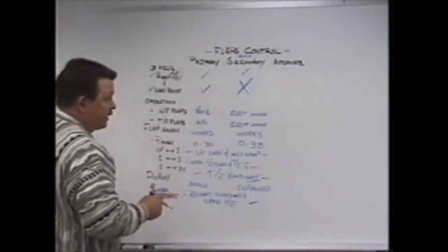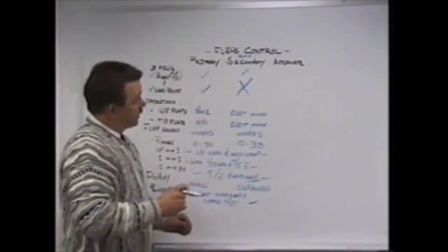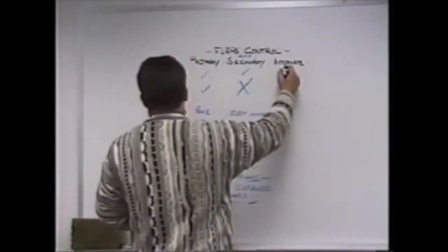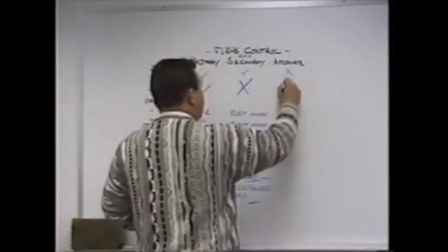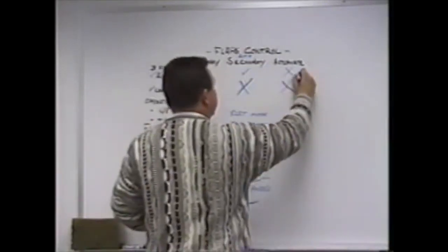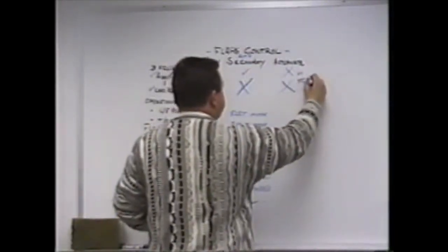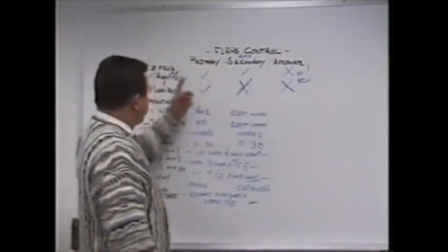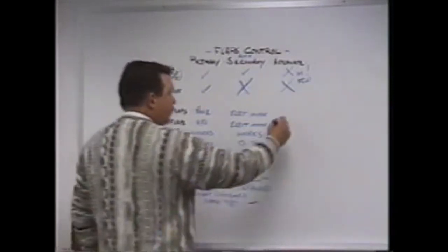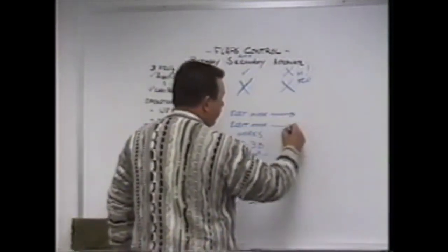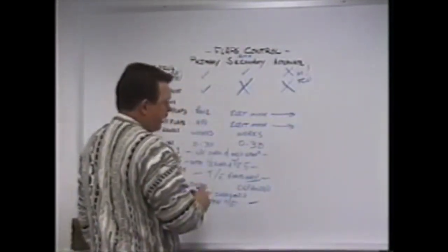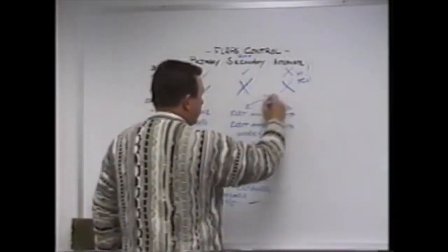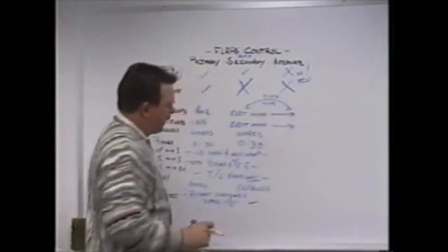Alternate mode, on the other hand, is a different story. When you press the alternate flap arming switch, that will shut off the 3 flap control units, and as a result you have no asymmetry and no load relief. There are no flap control units. You shut them off, and that protective feature comes from those 3 flap control units. You're still using electric motors to drive out the leading edge and trailing edge flaps. However, it's different wiring. So it's a different control wiring out to the electric motor.